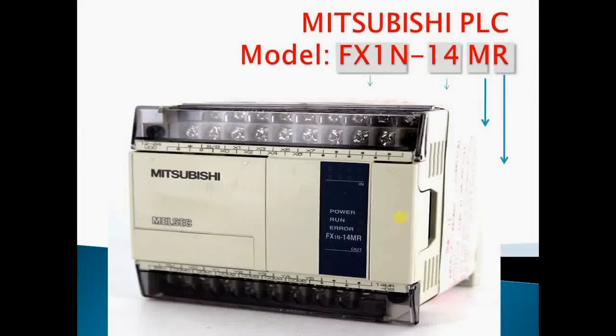Hello guys, I'm going to show you a tutorial on Mitsubishi PLC. Here you are seeing a Mitsubishi PLC, and the model is FX1N 14MR. FX1N represents the PLC series, the PLC type, and 14 represents the total IOs that the PLC contains.